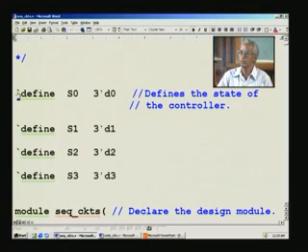So you say define, and this indicates the state machine. Finally we will be seeing a state machine model, and in that we have used S0 through S3 for the states. So we can list all of these here, and while writing the code we can deal straight away with S0 and not the actual number. It is cumbersome to use a number at every point, so it is always easy to use a symbol like this, any meaningful name.